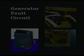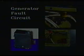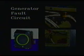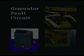The generator fault circuit is almost identical in operation to the battery fault system. Although unlike the battery fault system, the two circuits are totally isolated and independent. The components of the fault system include transformers installed at each end of the major generator wires and the components of the fault circuitry itself, which is contained inside the control panel. This system functions exactly the same as the fault system discussed during the DC power distribution programs.